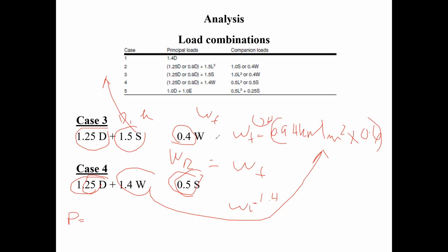Because this is your wind load, you understand? And then your wind load now is in kPa. And the tables give you a WR value, which is in pounds or kilonewtons per meter. And therefore, you have to convert your wind load into a WF value. And how do you do that? You multiply by the tributary width that each stud carries. So you're on the right track. How did that sound?